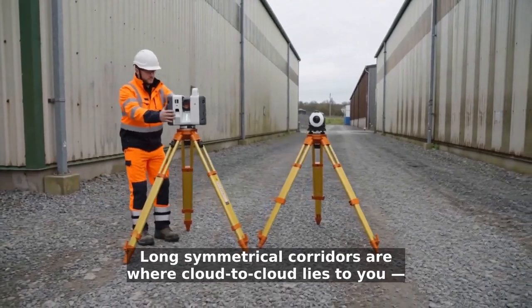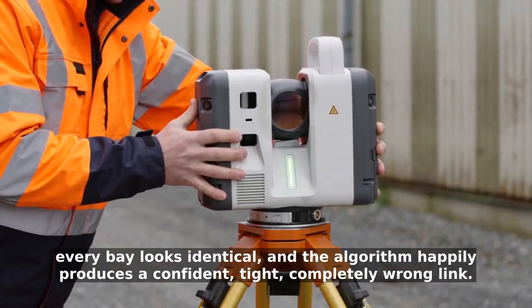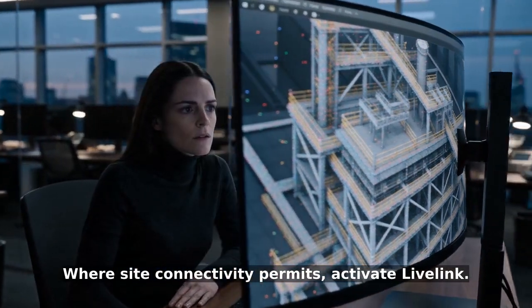Long symmetrical corridors are where cloud to cloud lies to you. Every bay looks identical, and the algorithm happily produces a confident, tight, completely wrong link. Use targets there. Where site connectivity permits, activate LiveLink.